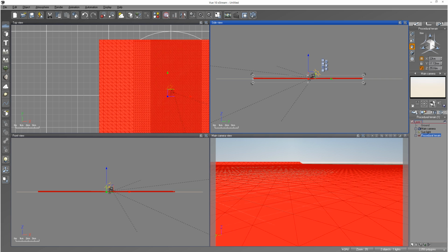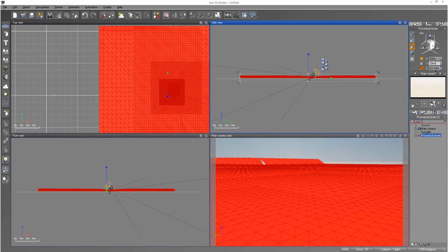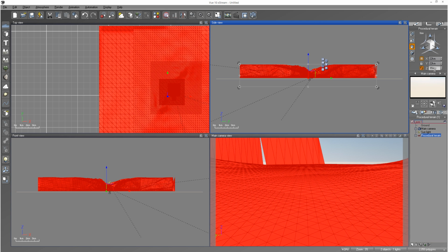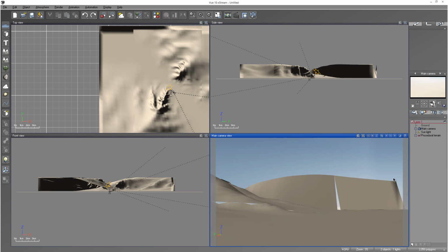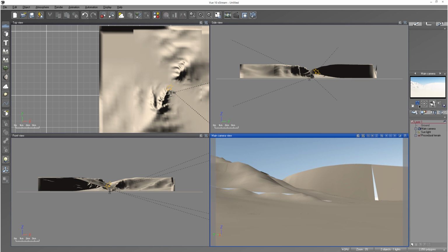There we go. And the height, or let's see, 22 kilometers, 22 kilometers, and I don't think we had our highest setting at 3,500, but we can change that to 3,500 meters. And now the terrain will be up to scale as what we had in Geo Control.